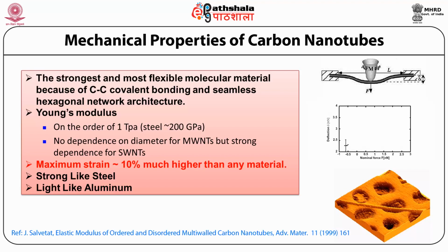The table in the slide summarizes the calculated Young modulus, tube axis elastic constant and tensile strength, and is in agreement with the experiments on average. Experiment results show broad discrepancy, especially for multi-walled nanotubes, because multi-walled nanotubes contain different amounts of defects for different growth approaches. We have many methods to grow MWCNT and, depending on the temperature and other parameters, the amount of defects varies, and therefore the properties of MWCNT vary from growth method to growth method.